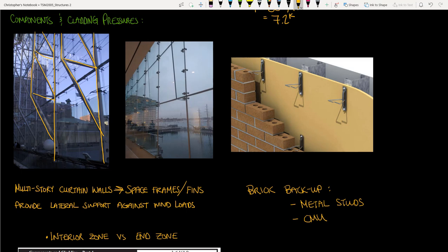When using brick, we are clearly trying to achieve very different goals architecturally, and so we need a suitable structural system to match. Unlike glass, brick is a porous material, and so there is greater risk of moisture entering the building. Hence, the architect will need to include a cavity behind the brick to allow any excess moisture that may get behind the brick to evaporate.